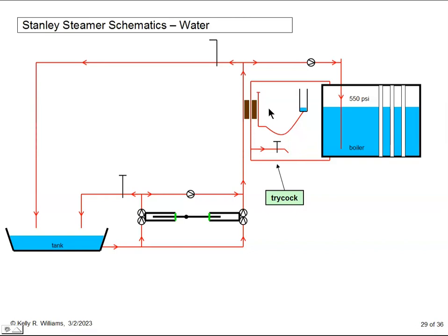To test the 3-tube indicator, we open the tricock. Steam pressure here pushes the water down out of the column, heating up the area connected to the standpipe. This simulates a low water condition, and we should see the water rise in the glass. Note that it will not fall back immediately when we close the tricock. We need to get the car moving so that feed water starts moving past the boiler column and cooling it back down. This usually takes less than a quarter of a mile of driving to accomplish.